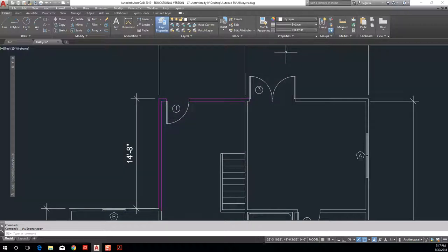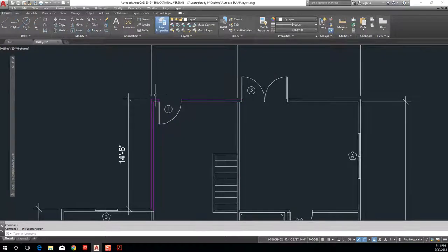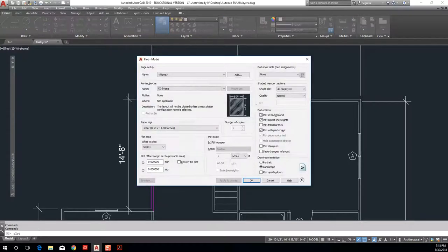What I just did is called loading your pen file, right? So now that file that defines what our colors mean in AutoCAD is there, okay? And this is not something you're going to have to do for a little while, right? But when I go to print something now, the LaserJet CTB file shows up in my print dialog box. That's how we're going to use it.